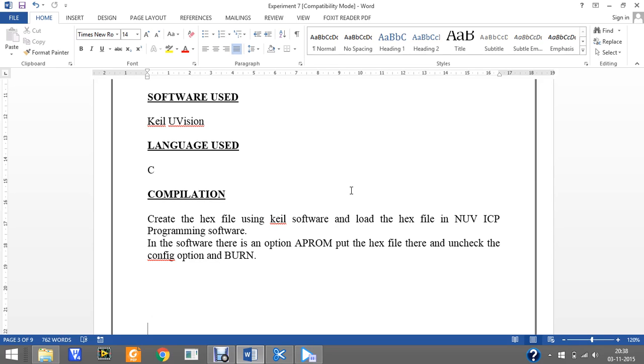In port A, I2C protocol pins are there. In port C, SPI1; in port D, SPI2 and CAN lines. There are 3 PWM signals and RGB LEDs attached to port A. There are 4 LEDs connected to port C and a switch is connected to port B.